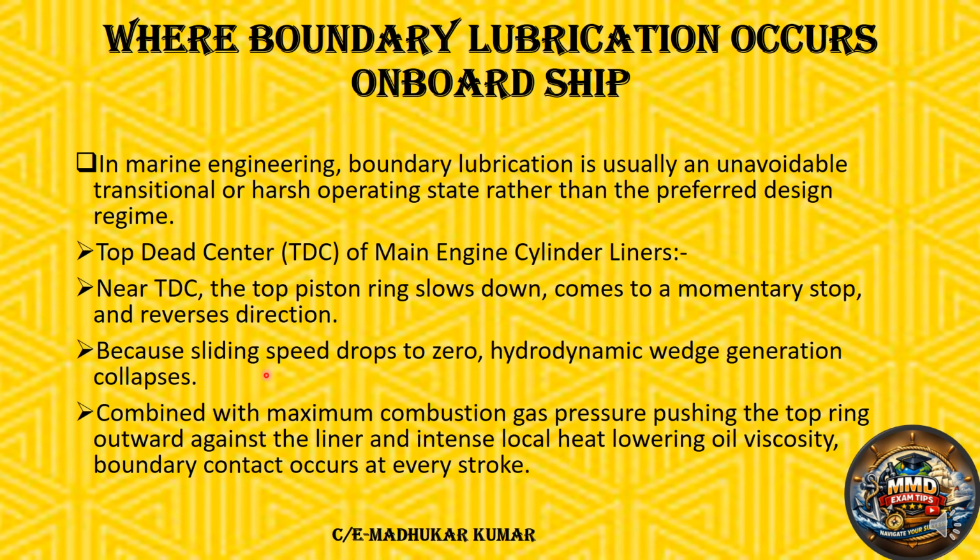Because the sliding speed becomes zero, the hydrodynamic wedge generation collapses, and then boundary lubrication starts. Combined with maximum combustion gas pressure pushing the top ring outward against the liner, and intense local heat lowering the oil viscosity, boundary lubrication contact occurs at every stroke.